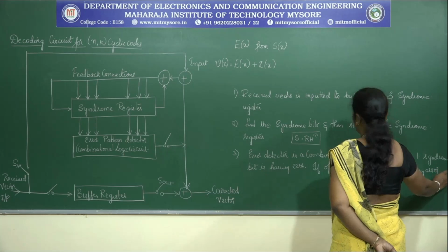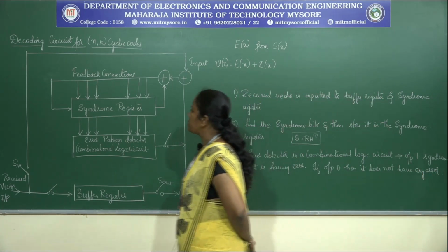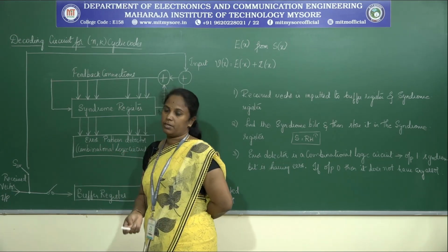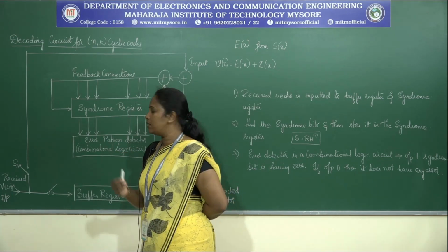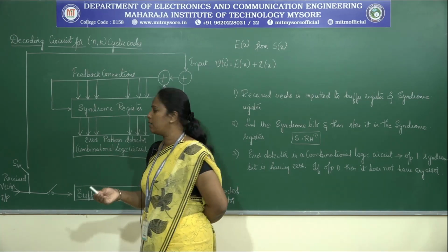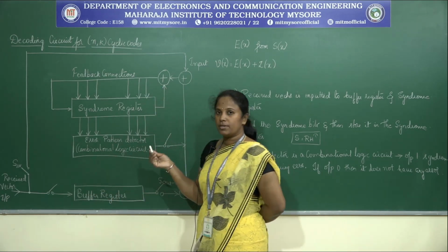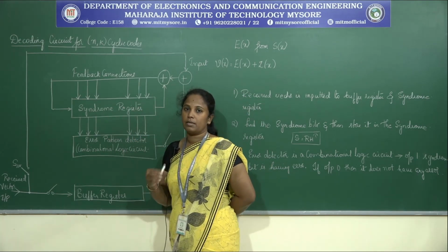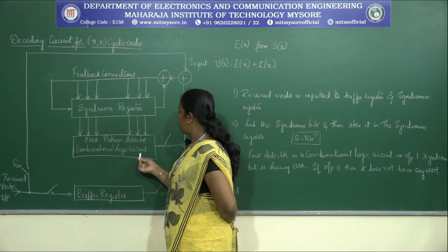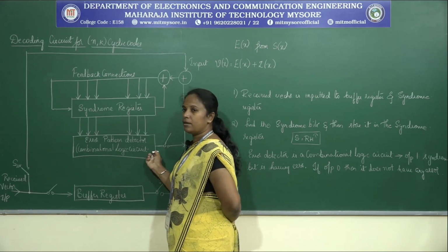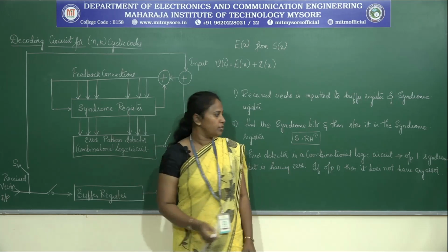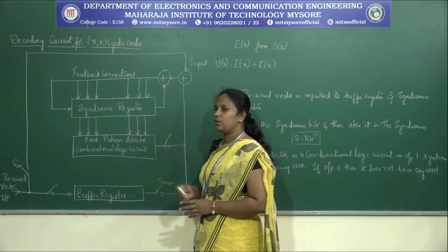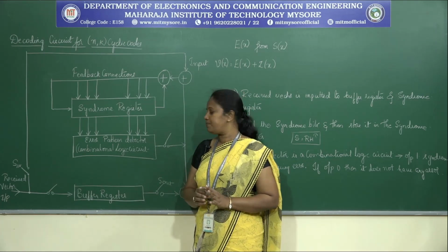So you are going to detect bit by bit. You are not going to consider the whole received vector, but in the syndrome register, whatever syndrome bits you have, you detect them bit by bit. If the output of this pattern detector is 1, then we say that we have an error. If the output is 0, then the received vector is correct.